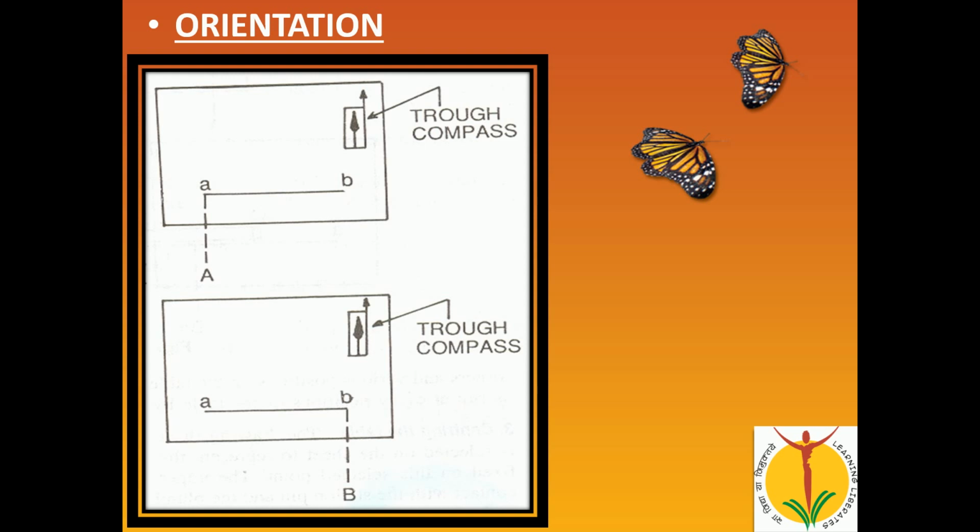So, orientation by using the trough compass. It is a simple method. In this method, we have to level the table properly, then place the trough compass on the plane table, and the trough compass will show the north direction. We have to mark the north direction with the help of a pencil. Then you move the table. Suppose you have placed the plane table at A, and you are going to bisect the point B, so you have to draw one line. Our ground station is capital A. From this you mark the line, and you bisect the other station B. Now when you move the table from station A to station B, you have to place the table exactly over the ground station, because small b is a point on the drawing sheet. That point you have to transfer onto the ground station at B. With the help of the U fork, you transfer this point B onto the ground point.